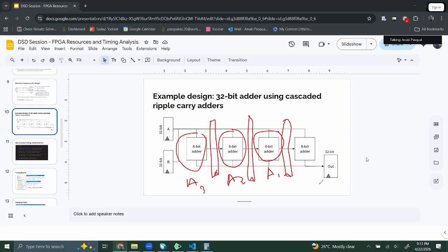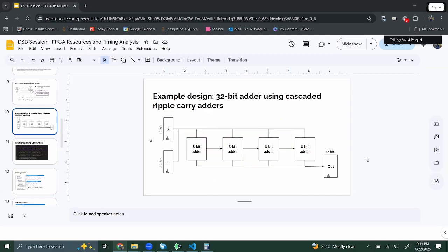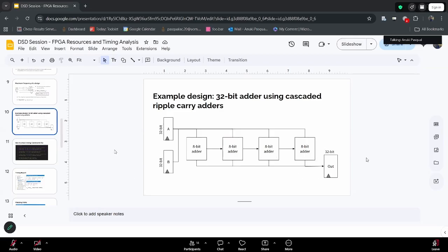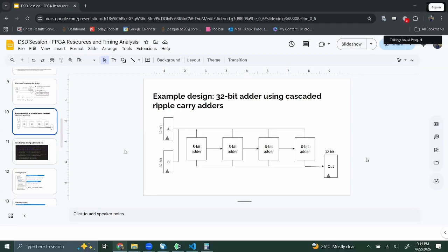But immediately after that, we will get A2 in the next cycle, and in the next cycle, A3. So then the delay between iterations is still 1 clock cycle. So the throughput will be the same. The latency will increase. But normally, in a lot of processing systems, throughput is what matters, because then we can run lots of iterations without losing efficiency.